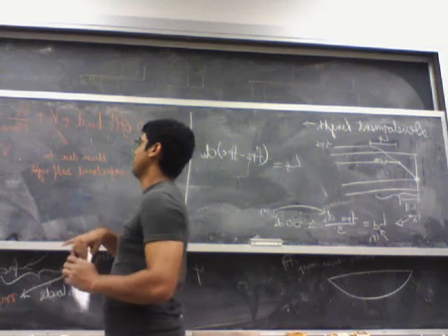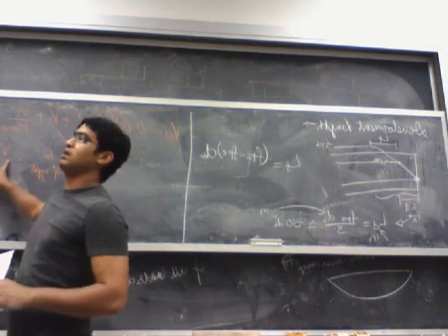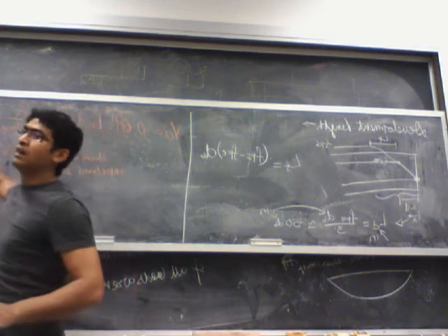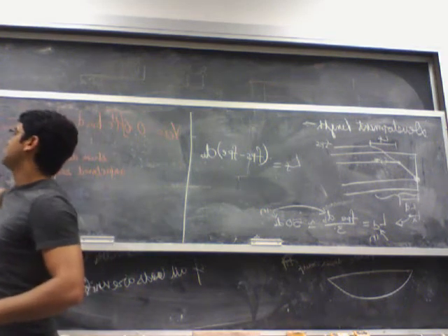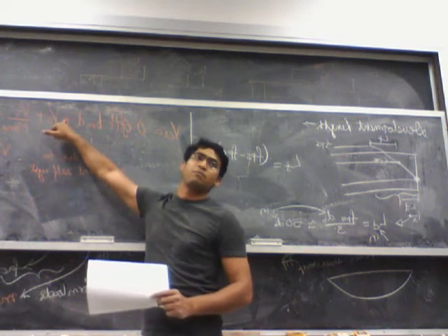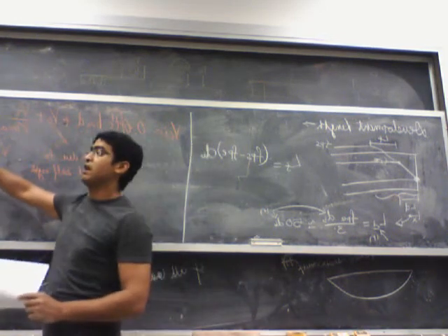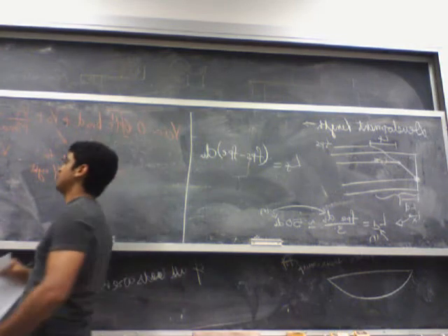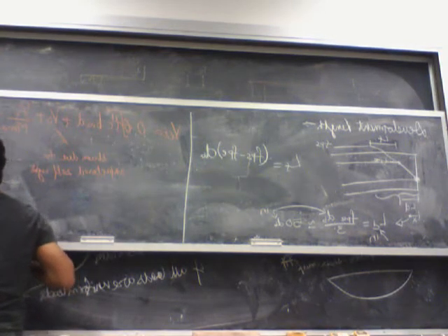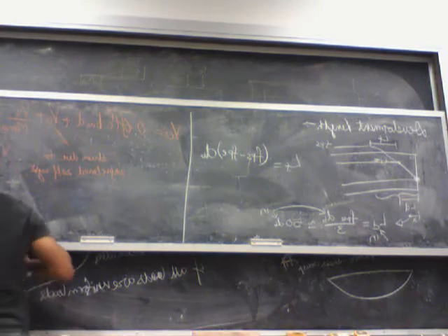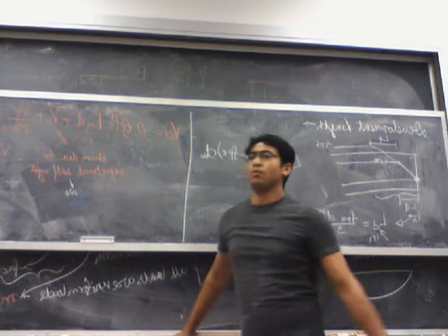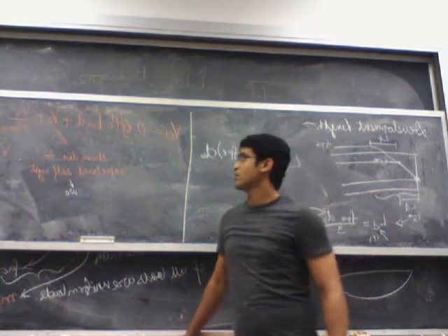It's alright. Oh, okay. So V_i is the shear at that particular cross section due to all the loads except the self weight, because the self weight is already accounted for in this V_o. And all these are calculated based on the factored loads. So it's 1.2 times the dead load plus 1.6 times the live load. And this is simply your self weight, omega_o, without any factors.